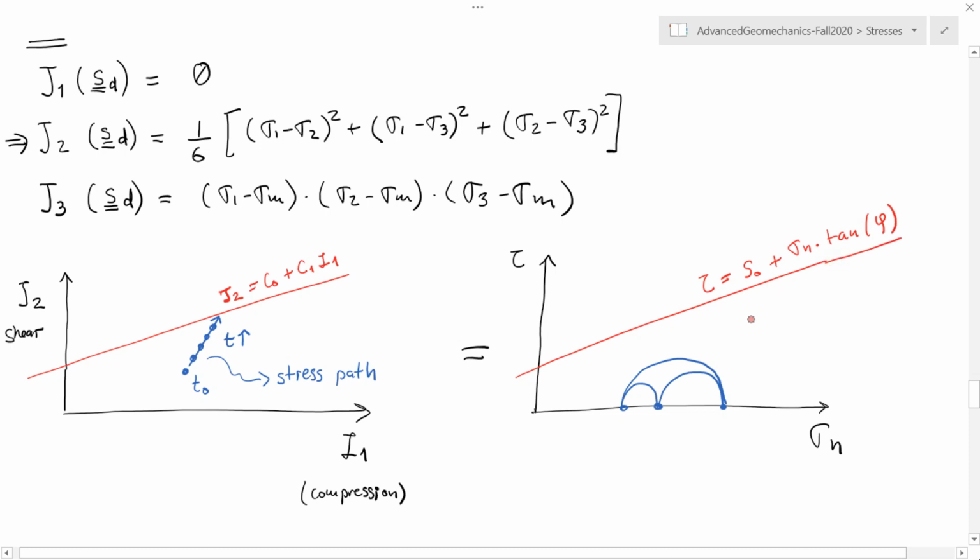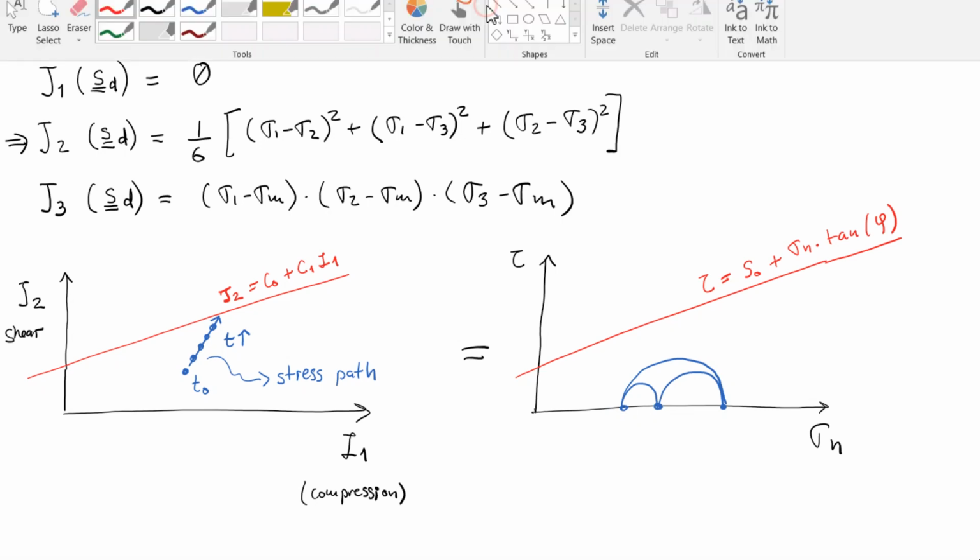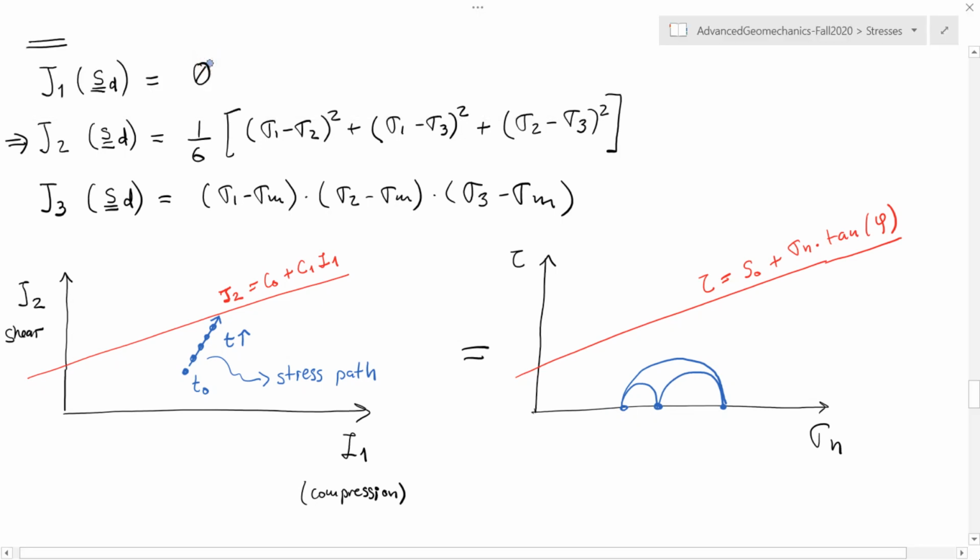The plot on the right is almost exactly the same as the plot on the left. But on the plot on the left, I have reduced 3 circles and 3 principal stresses to just 1 point. But it is exactly the same thing. If I wanted to plot this as a function of time, then this Mohr circle on all of them will move in the direction in which is shown in the arrow. But it's exactly the same.